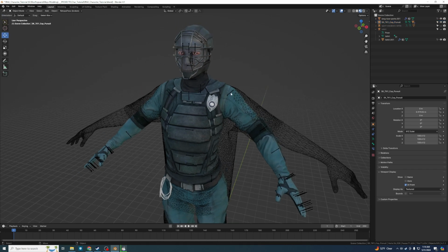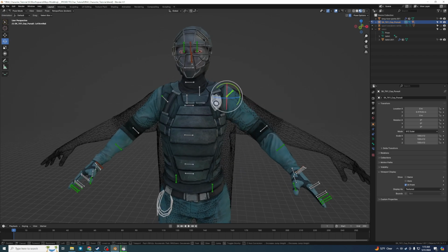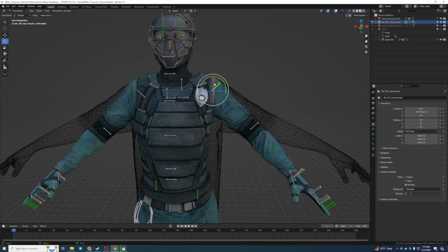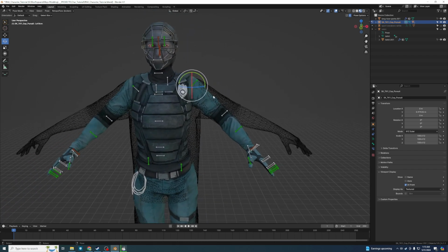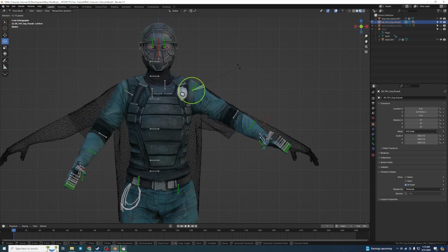What you need to do to pose stuff like this is click on the skeleton, go to object mode and change it to pose mode. In my case, I'm going to hit a hotkey a lot of the time, which is 3. I hit 3 twice actually to make it work because Blender 4.1 did some changes. Now if I move this arm around, you can see it's moving the model around. I'm moving around the arm roll, which I don't really need to do. We need to move around the arm. And all I'm going to do is try to pose him up in place.